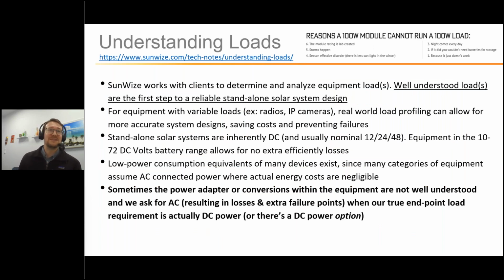So no presentation from SunWize would be complete without a cursory reference to understanding loads. All projects really start with understanding the load profile of the device to be powered. I'm sure no one here has made this mistake, but it bears repeating why a 100-watt solar module will not power a 100-watt continuous load. A couple of the reasons are, of course, that storms happen. Night comes every day. We also have seasonal affective disorder where there's less sunlight in the winter. And if you did, you wouldn't need batteries for energy storage.